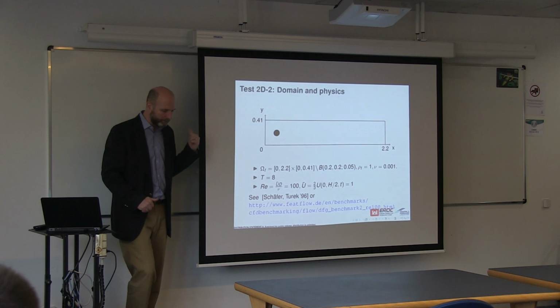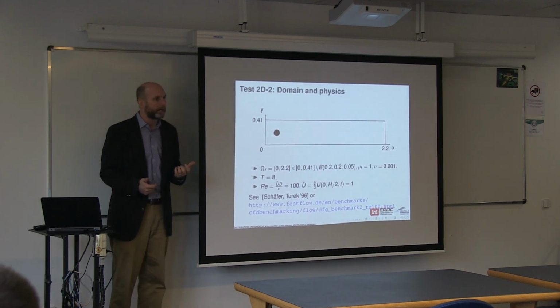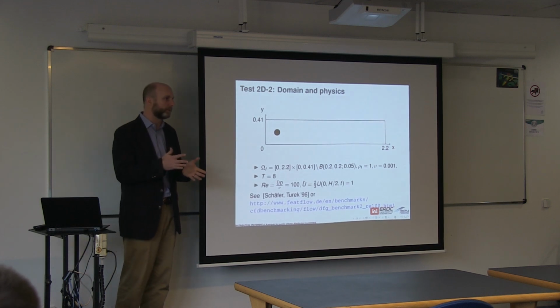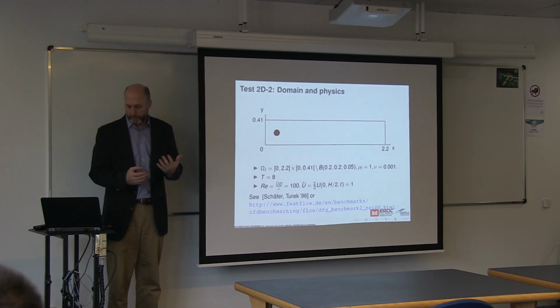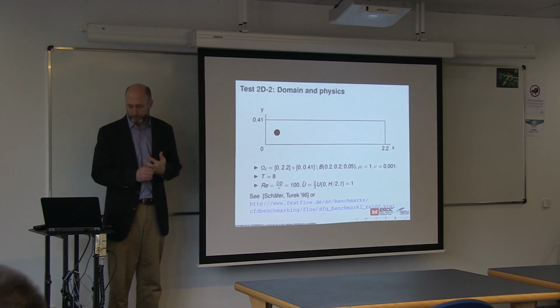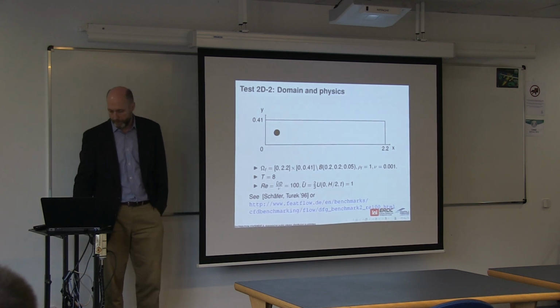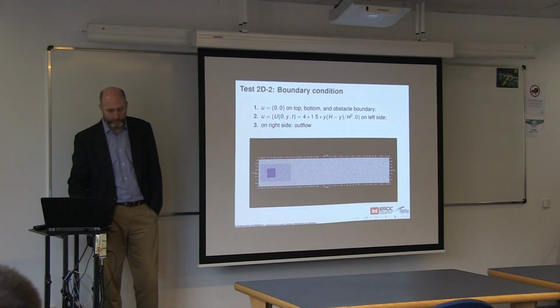However, when we were looking at these problems, we started to see a lot of noise in the calculation of the drag and the lift, and so we went back to some of the standard CFD test problems for simple geometry. Schaefer and Turek, of course, developed those a long time ago now, so those are nice benchmarks that are well known. And so we went back and recalculated those with the immersed boundary method.